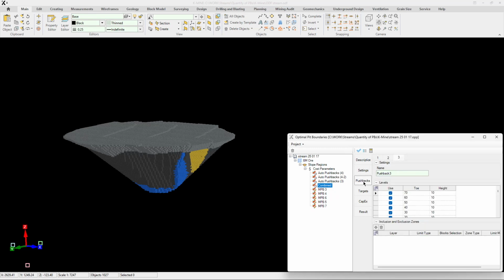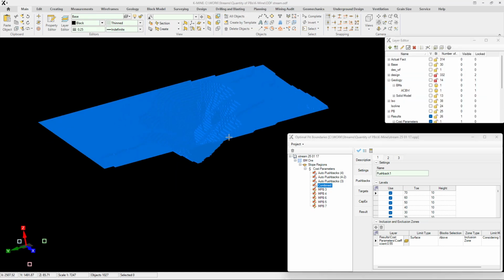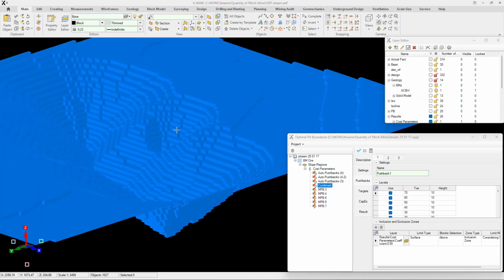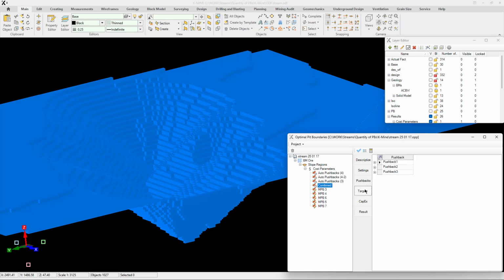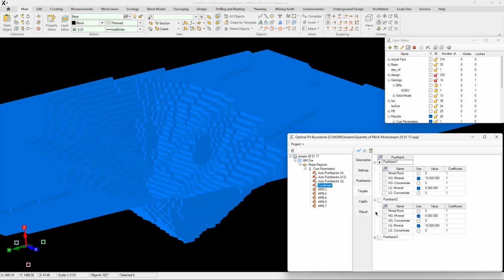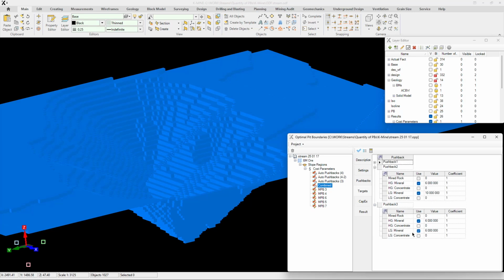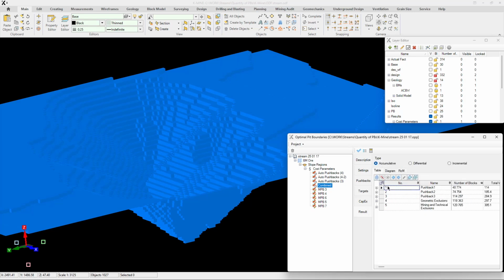If you add a spatial constraint, for example, define the first pushback manually, the rest can be generated automatically. This gives you more control over the first stages while still saving time on the rest. In our case, we used an open wireframe surface to lock in the first pushback and let the algorithm calculate the rest. There are also additional filters you can use to precisely control which blocks should or should not be assigned to a pushback. Getting these settings right, combined with a solid understanding of your deposit, often determines 75% of your success.